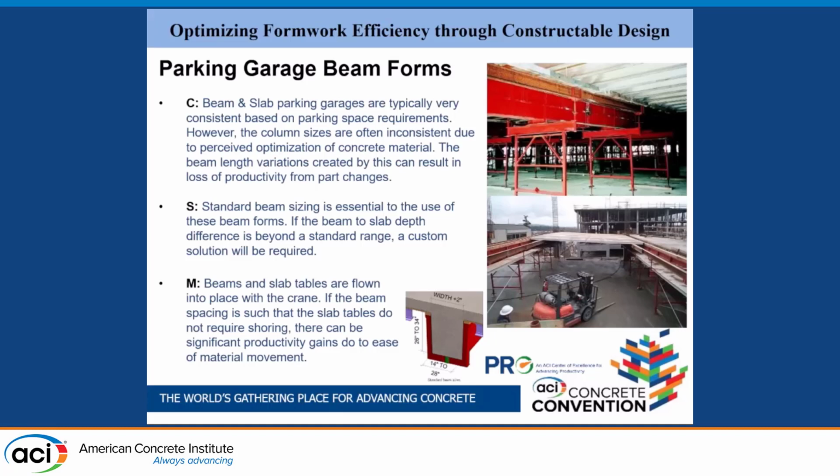So if the end columns are of different sizes and those keep changing floor to floor, now your beam size, or length, keeps changing floor to floor, and you have to change that and accommodate it, maybe not from level to level, but from bay to bay to bay. So now you're having to swap where you're putting these things as you move through the building, adding time to move parts and pieces, coordination issues as well.